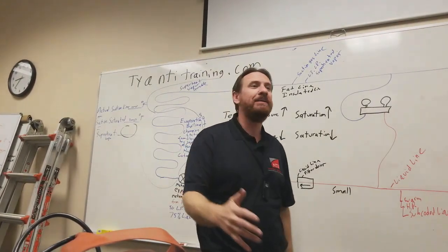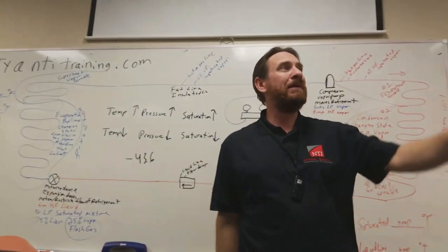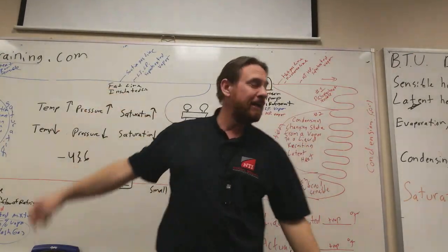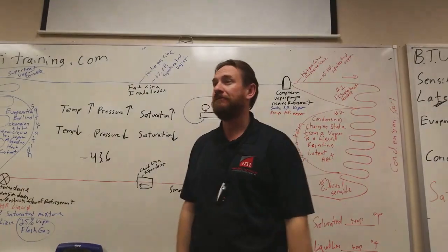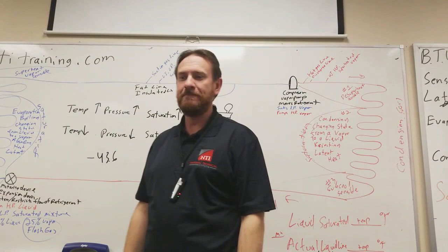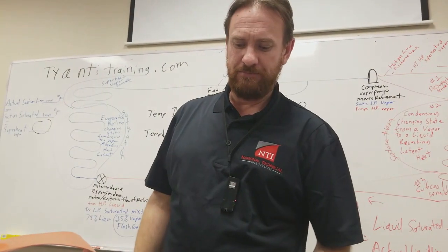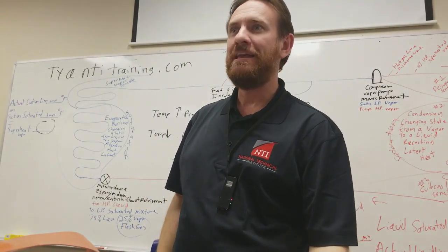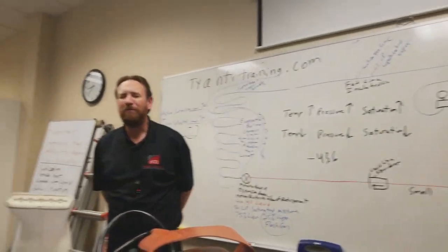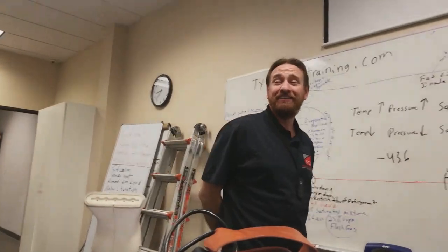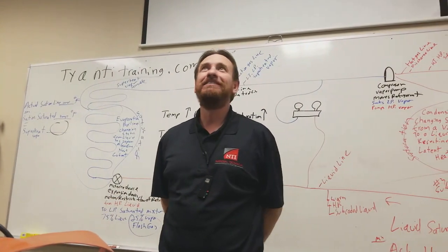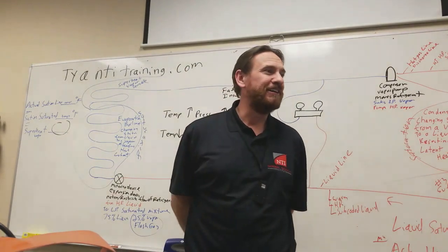So propane, yes, propane is a refrigerant. And propane has a temperature pressure chart just like that. And they use it, they find superheat, and they find subcooling when they're charging the systems. It's awesome. Absolutely is awesome. So cool. Propane doesn't deplete the ozone either, does it? Oh, there we go. Forgot all about that. Propane and its accessories do not deplete or destroy the ozone layer.